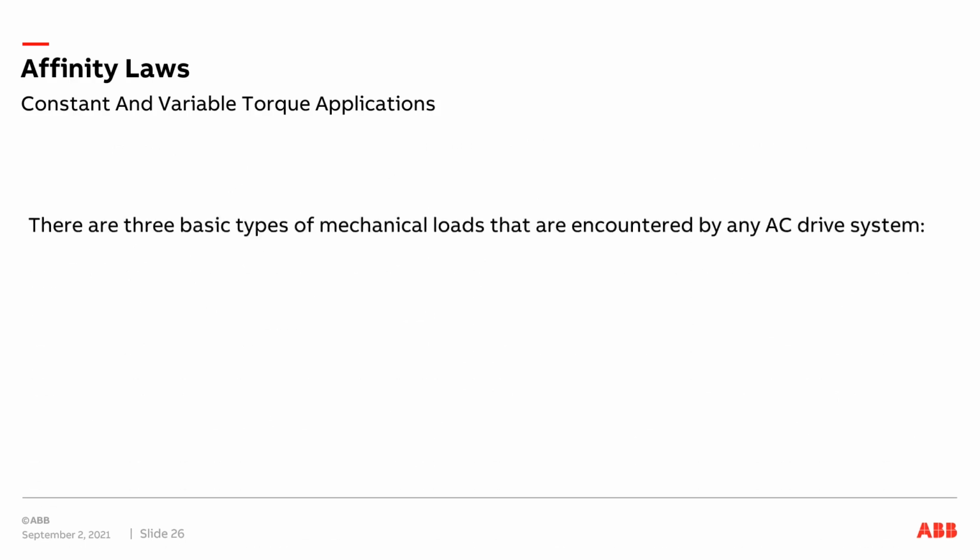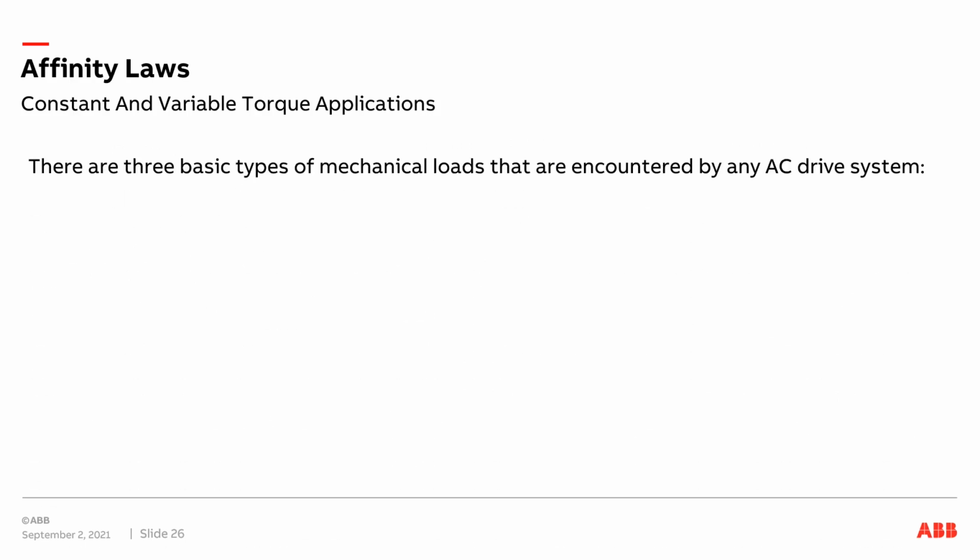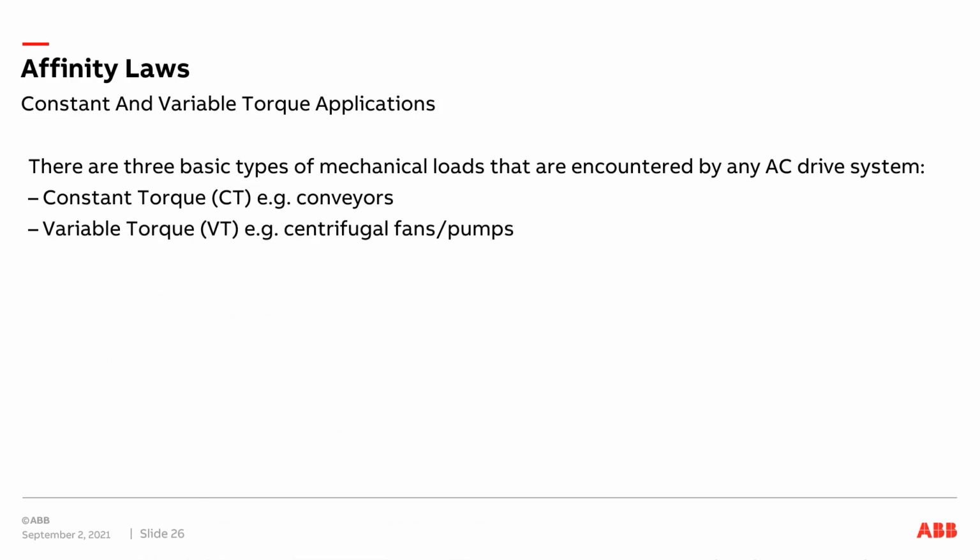Constant and variable torque applications. There are 3 basic types of mechanical loads that are encountered in an AC drive system. Constant torque, CT, i.e. conveyors. Variable torque, VT, centrifuge fans and pumps. And constant horsepower, which would be used in machine tools.